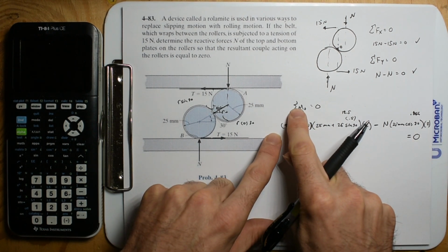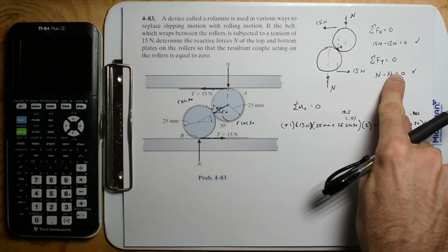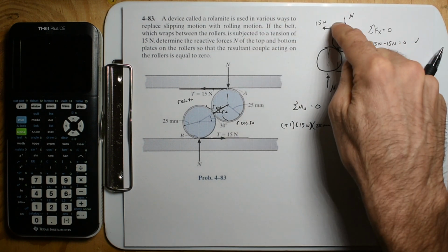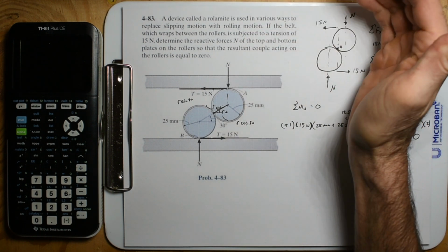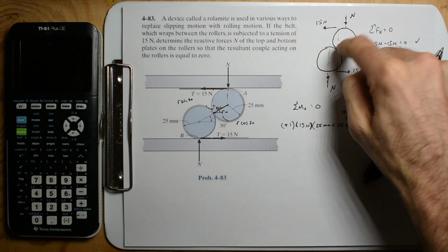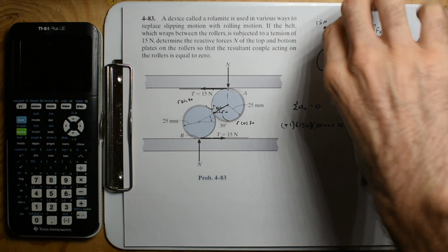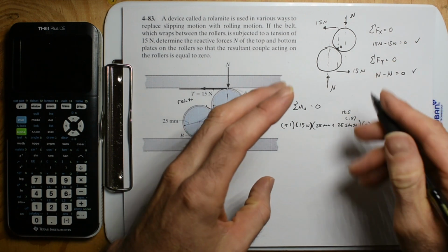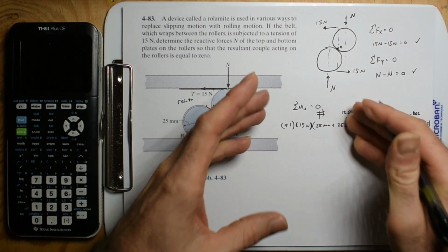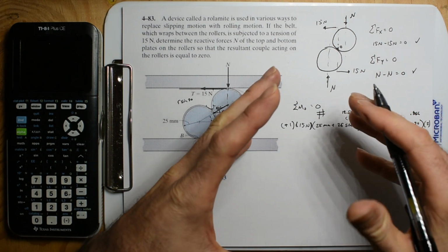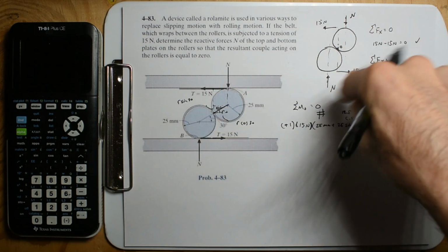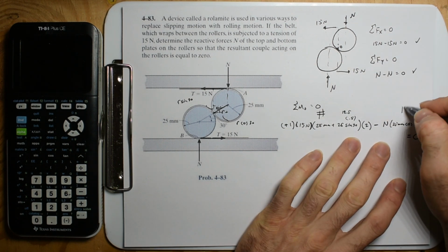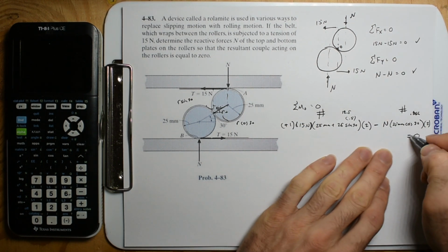So we sum the moments, just like we would sum the forces. This is a positive force, that's a negative force. So we've identified that this generates a positive moment, this one a positive moment, this one a negative moment, this one a negative moment. And summing those moments, those moments have values. The number is due to the leverage. The leverage is how much it would want to spin this thing. And so these two values have to equal 0.